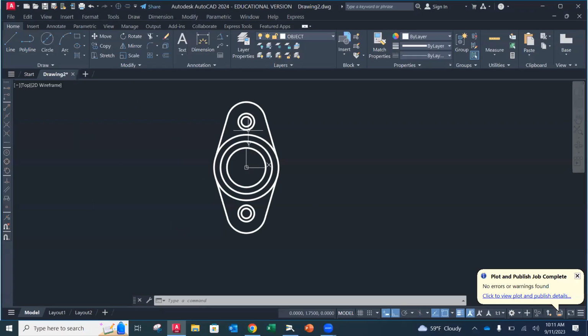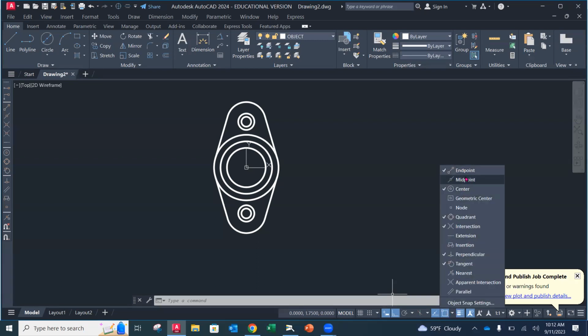All right, and remember the key here is we have to have everything in alignment. So what I want you to turn on is show snapping references. If you don't have it, it's just to the left of your object snaps. Also make sure that your running object snaps are on and that you have endpoint, center. I added quadrant because I found that I kept using quadrant all the time, especially when I'm going from my circle view to my side view to show the lines of the holes. And then I have intersection, perpendicular, and tangent.